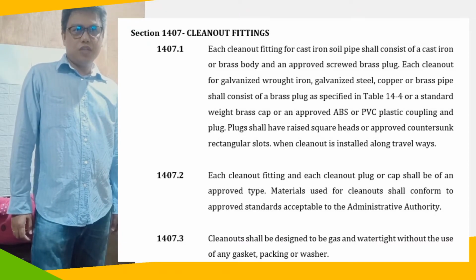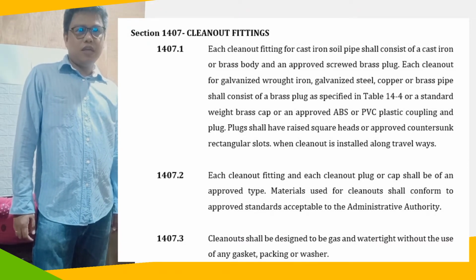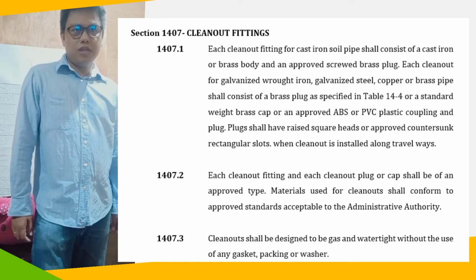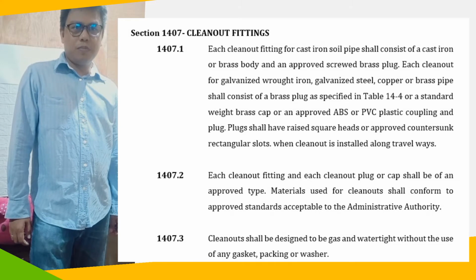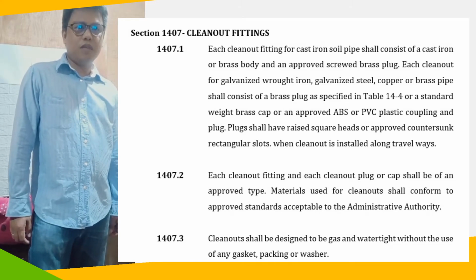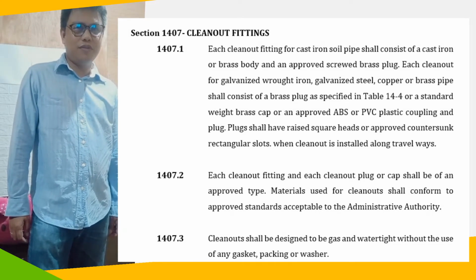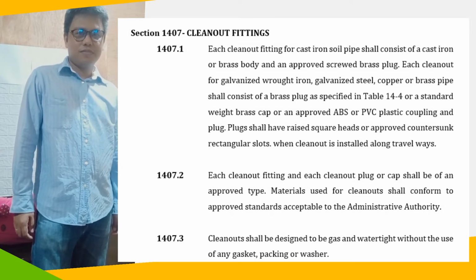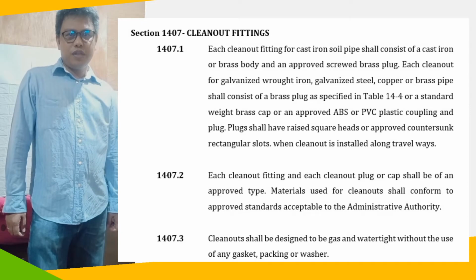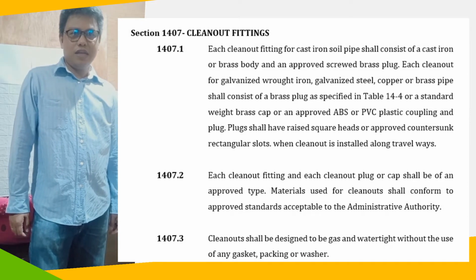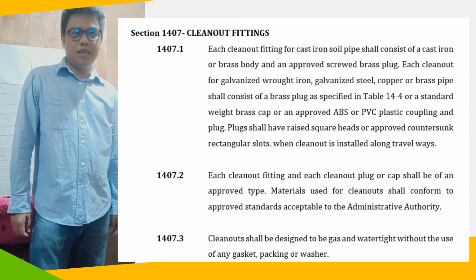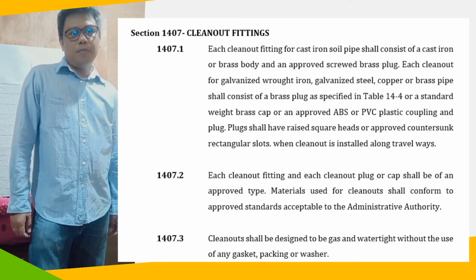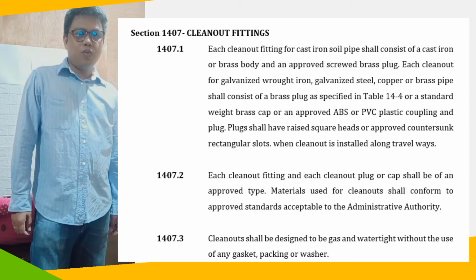1407.2 Each cleanout fitting and each cleanout plug or cap shall be of an approved type. Materials used for cleanout shall conform to approved standards acceptable to the administrative authority. 1407.3 Cleanouts shall be designed to be gas and watertight without the use of any gasket, packing, or washer.